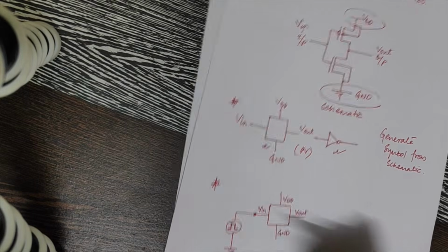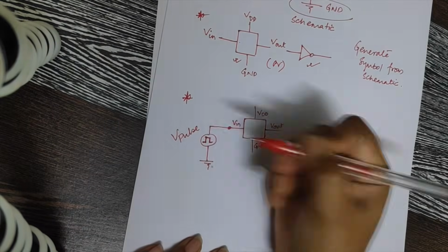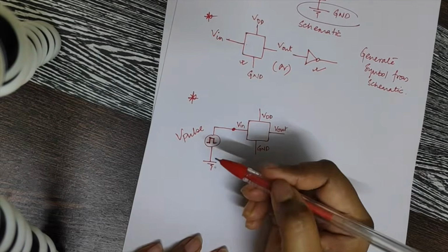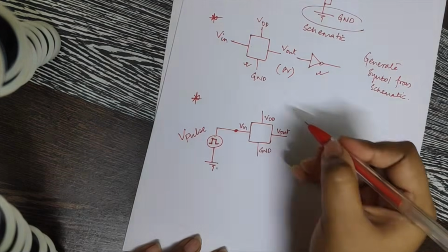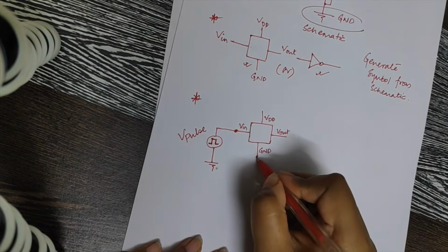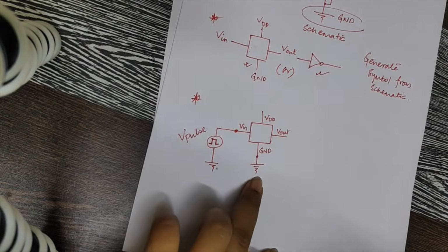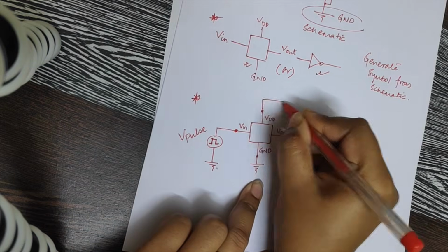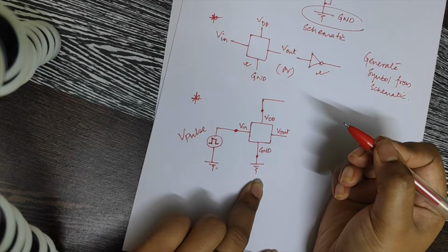Note, this is a pulse. So this voltage source is V pulse. I am using the actual name of the voltage source present in Cadence. So I need a pulse wave. Now for ground, I need to connect it with a ground terminal. This is the ground component provided by Cadence. For VDD, VDD is what? Power supply. If it is a power supply, another voltage source is required.